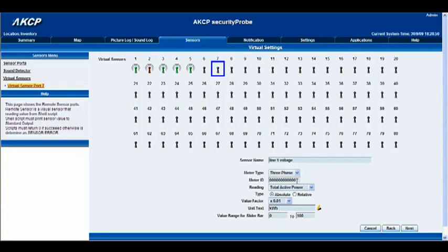Now if you look on the front of your energy meter, on the grey sticker, you'll see that in the middle of the grey sticker, just to the right hand side of the LCD screen, you'll see a white box with a number in it, and that is the meter ID. So before you type in the meter ID, you need to make sure that you type 0000 followed by the meter ID. So in my case it would be 11083796.